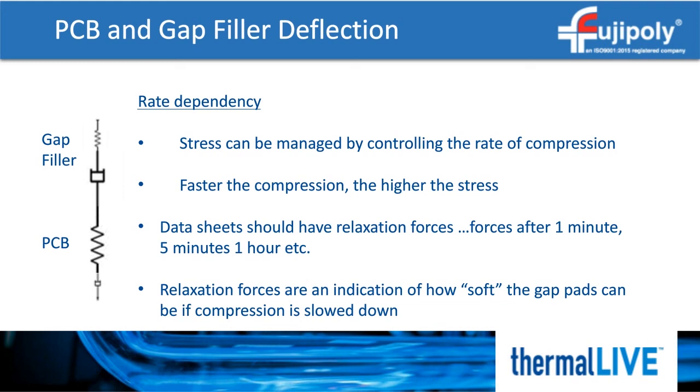If you see that the force after 1 minute at 50% is much lower than the force at 50%, then there's some room to reduce the stress by simply reducing the rate of compression or using a fixed load that will compress the pad to a given gap over time. If the forces are equal, that's usually an indication that the material is highly elastic. If that is the case, controlling the speed won't do much for reducing the stress.